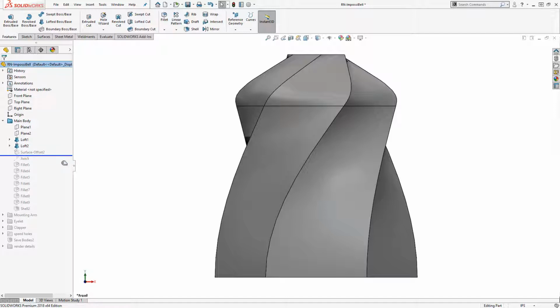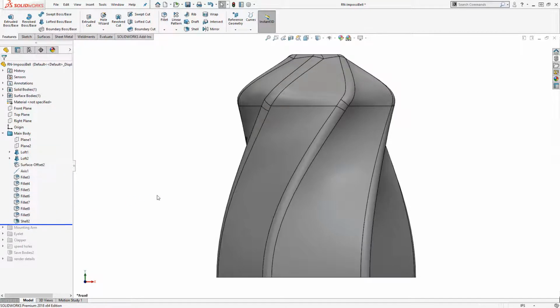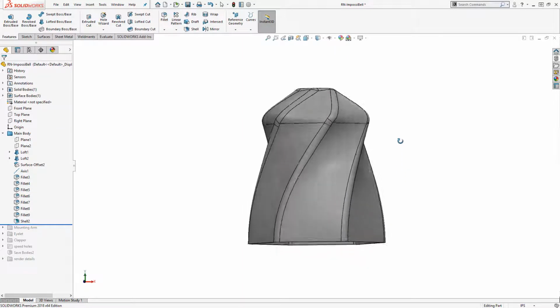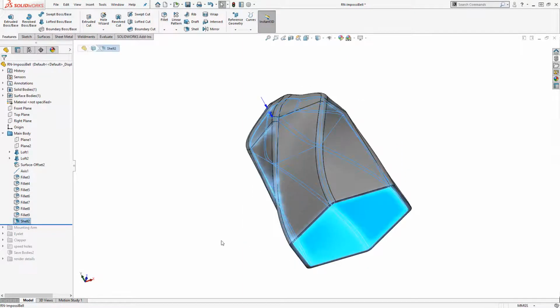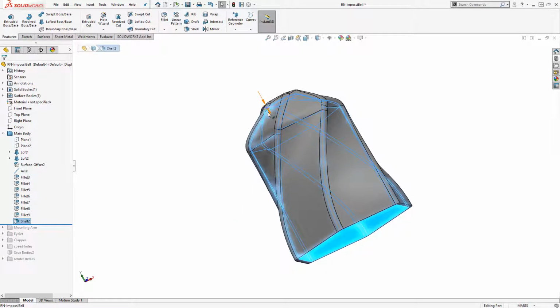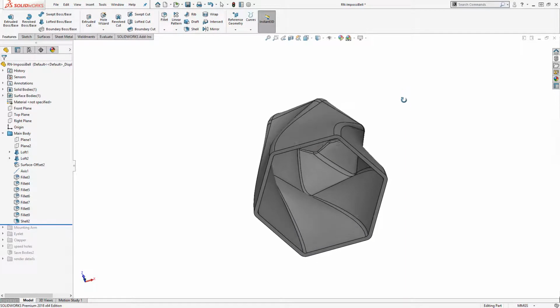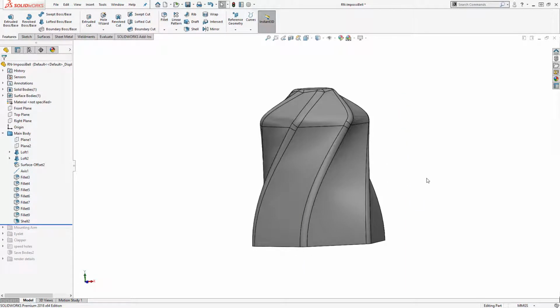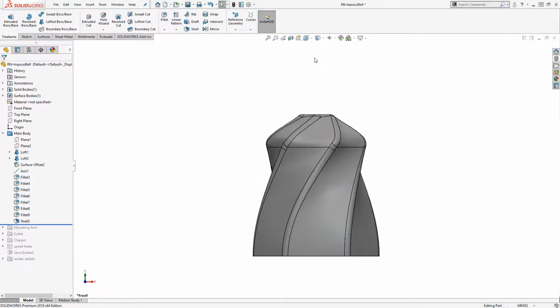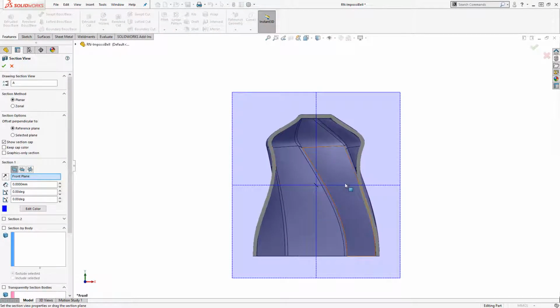And then we can see if we just roll down, it's just a lot of face fillets and a shell operation. I shelled this out to a 1mm wall thickness. And the HP 3D printer that this was printed on can actually handle even finer walls than that, but I thought that was a good balance. So again, if we look at it from a side view here, we'll see the cross section. We can see that it's a pretty complex profile.